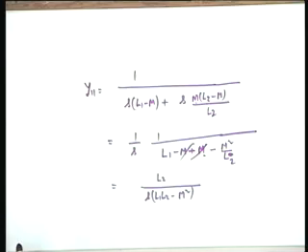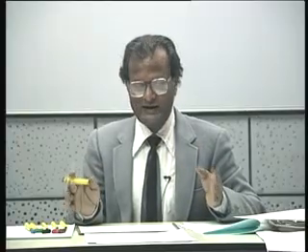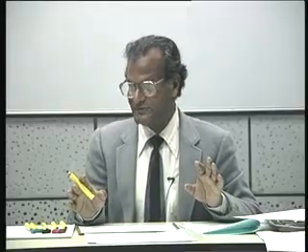If this was a perfect transformer, what would have happened? Y11 would have been infinity. In other words, for a perfect transformer, the Y parameters are not defined. Similarly, you can find the other two parameters, and I repeat, in this case you can apply the T equivalent circuit to derive the Y parameters, because that is your limited objective, but do not dare to do anything else, because you might destroy your transformer and also whatever you connect to. That's all for today.